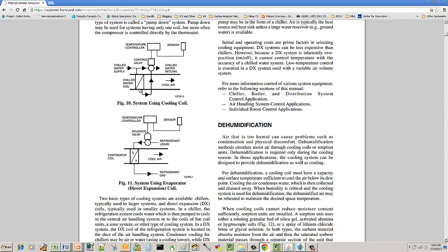Oh wow, doesn't this look similar? Yes, if you've mastered a hot water valve, you can understand a chilled water valve. The big difference is hot water valves typically control between 90 to 140. Electric heat coils may get up to 160, 180. Chilled water coils typically control to, if you've got a 42 degree supply, ideally you want a 55 degree discharge. When you're talking fan heat gain, you're looking at a 50 to 52 degree discharge off a chilled water coil.